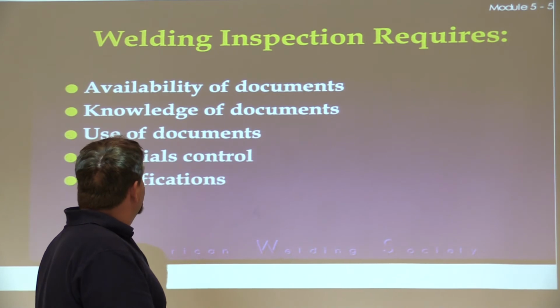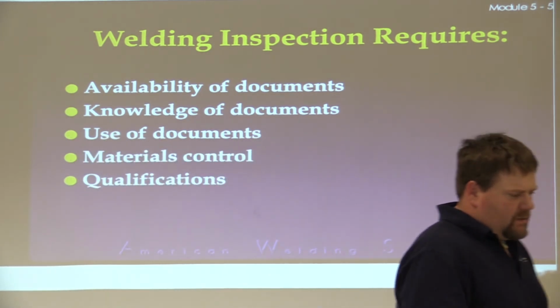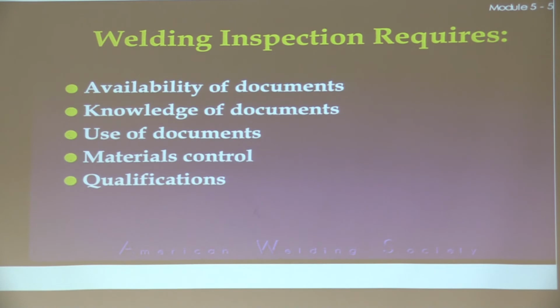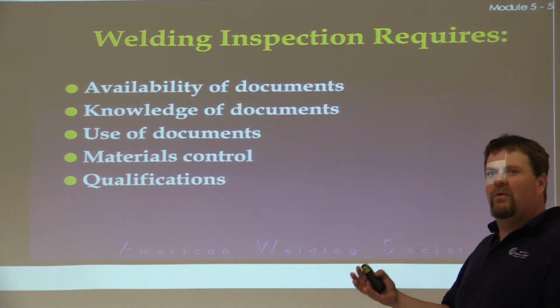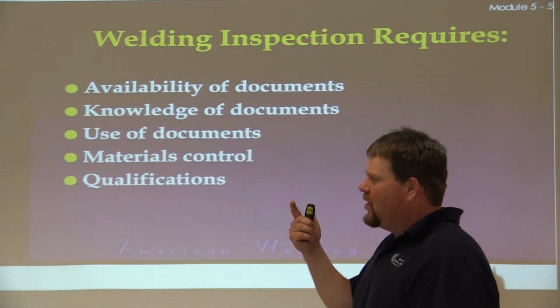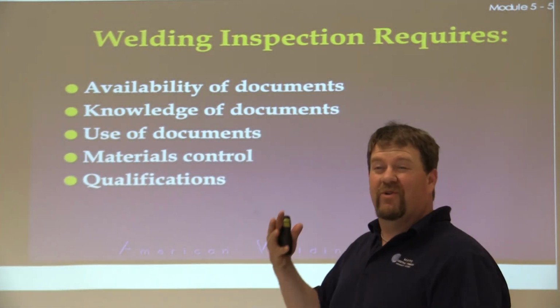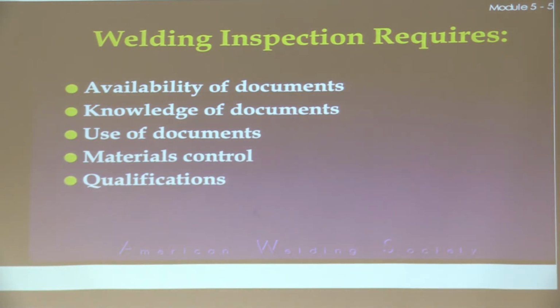Know your specifications. So, moving on to page 5-27, we're going to talk about our weld joints. And the throat of the weld is vertical, horizontal. Most of you have talked about this or with me by this point, whether it's a 1F, 2F, 3F, 4F, 1, 2, 3, 4G, groove weld, or anything like that. Okay. Page 5-27, right-hand column talks about the TKY. Helps explain that better. 5-28, 5-29, you can look at your different fillet welds or socket welds.